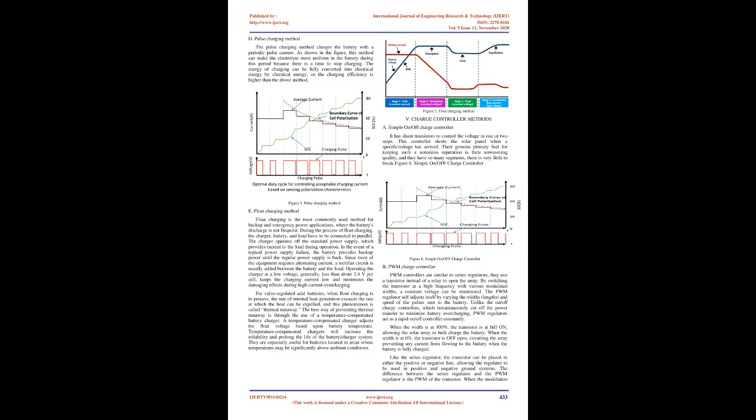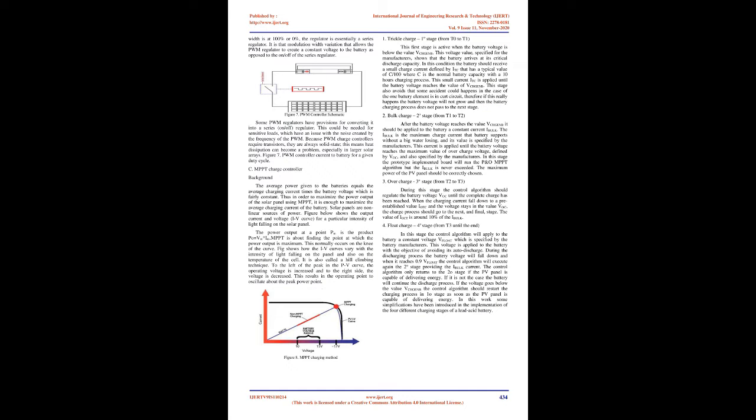Deep cycle batteries have thicker electrodes than the standard starter batteries. Gel batteries and sealed lead-acid batteries are commonly preferred to store solar electric energy for off-grid applications. About 93% of lead-acid battery is recycled to make new lead-acid batteries. The self-discharge characteristic of the lead-acid battery is relatively high. At a normal room temperature of 20 degrees Celsius, the self-discharge rate is around 3% per month. Theoretically, a lead-acid battery can be stored for up to 12 months without a recharge. However, at higher temperatures, the self-discharge increases.